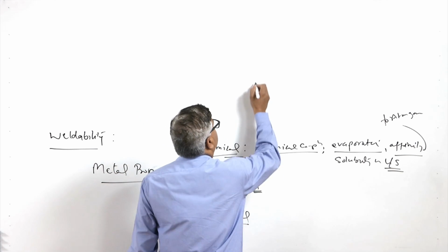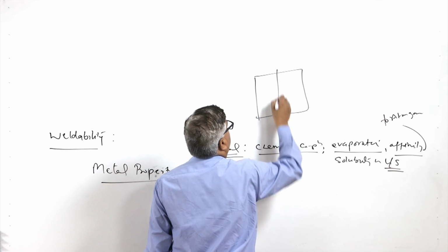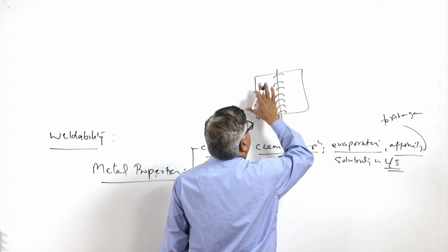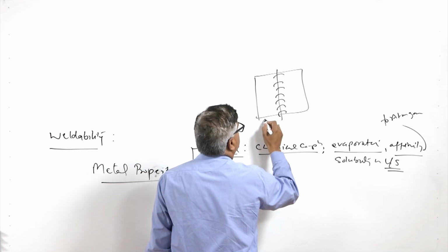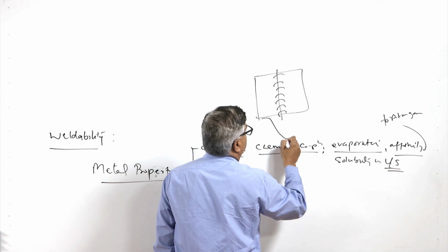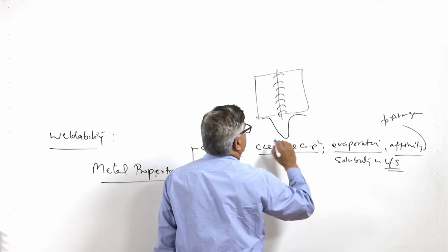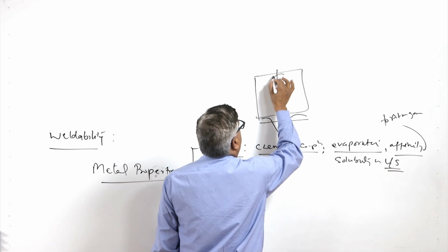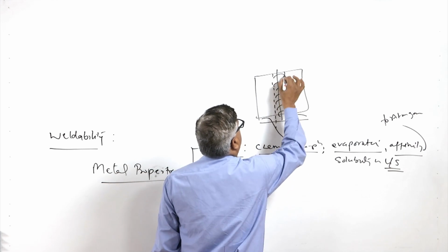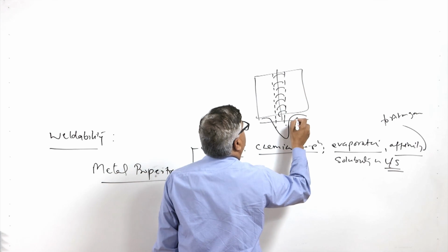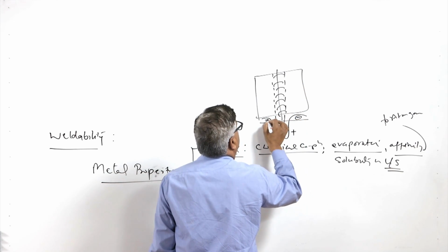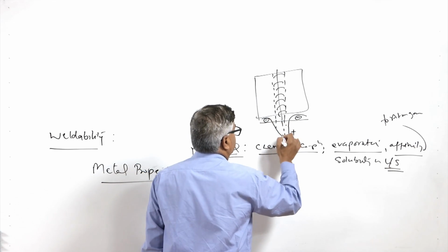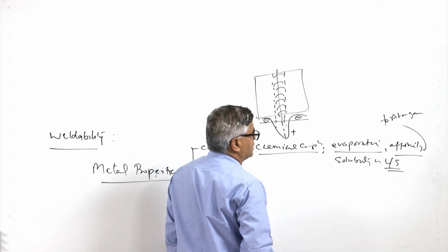So, with regard to this, whenever any weld joint is made like this, along the weld line we have residual stresses as well as in the transverse direction. So, the distribution of the residual stresses in the transverse direction can be observed like this, wherein the tensile residual stresses are found near the weld metal, while away it is the compressive residual stresses in the heat affected zone as well as in the base metal. So, maximum tensile stresses are observed at the center line of the weld.